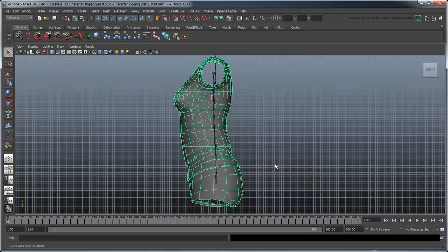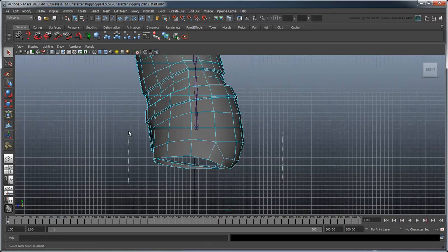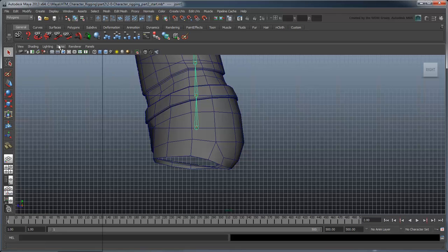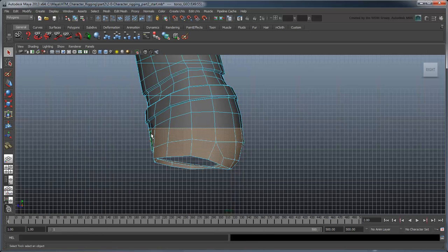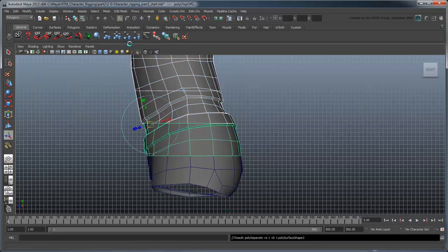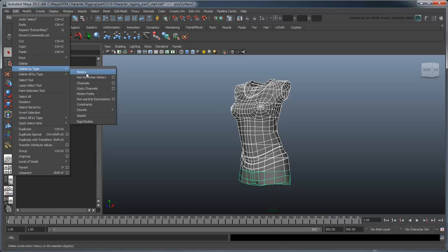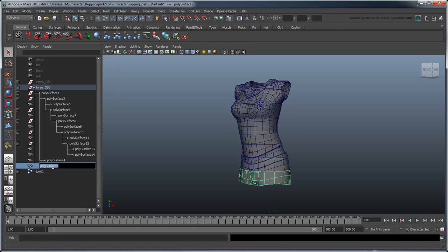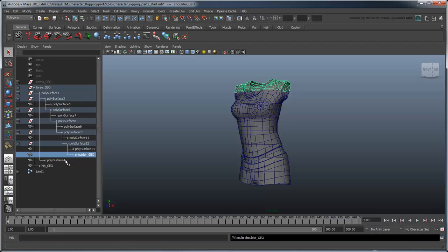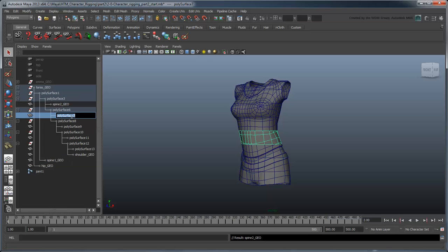Now, just as you did with the arms, legs, and head, select the faces of each section of the torso and extract them. You can turn off Show Joints in the workspace if you find yourself accidentally selecting them. As before, delete the history for each object and then rename them. Name the bottom portion Hip Geo, the top portion Shoulder Geo, and the sections in between Spine Geo 1 through 6. While you're at it, rename the joints to Spine Result Joint 1 through 7.